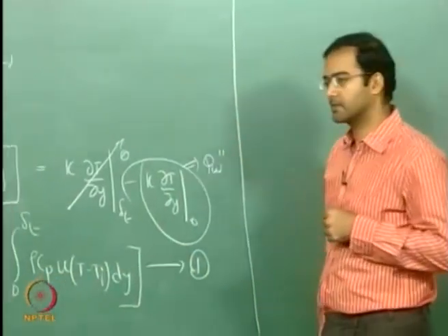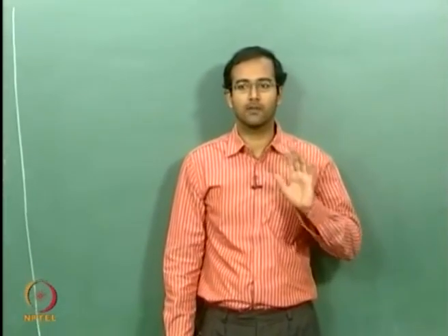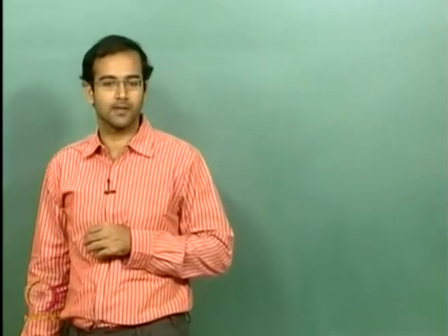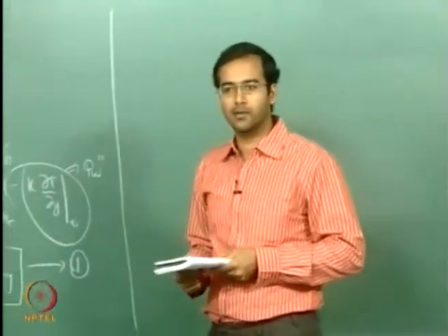As far as the velocity profile is concerned, we are not going to solve the momentum integral, because it is now hydrodynamically fully developed. So we cannot guess any velocity profile, but we have to take the exact profile as it is. Because if we had guessed a profile and applied the momentum integral, that would be valid only in region 1, and that too in the developing section. Once it is close to becoming fully developed, those profiles are not valid, and we are looking at region 2 now. So we cannot guess anything for velocity, we have to take the exact parabolic profile, okay.